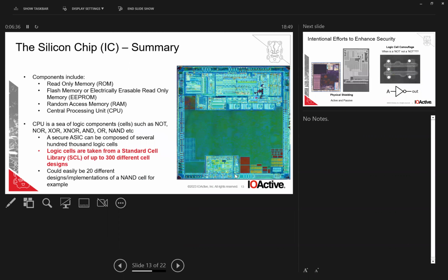So if we look at the floor plan of the chip, you can understand what is going on there. And really, it's how I describe it. It's just like a PC. You have this big messy area in the middle there, and that's the CPU. The rectangular blocks are just memories of different types. There'll be a flash on there, there'll be RAM, there'll be ROM, and maybe some fuses. But the CPU is the kind of the engine, which is doing all the computational functions. It looks like a mess, but it's very, very carefully laid out. Trust me on that.